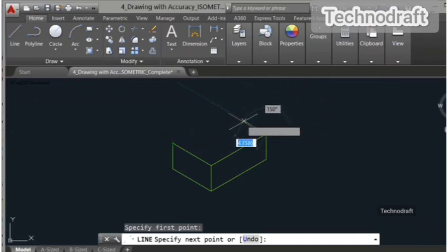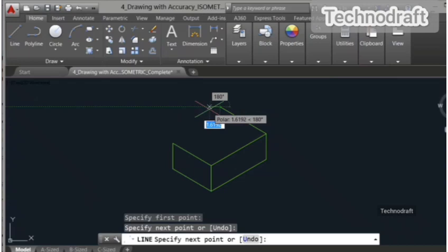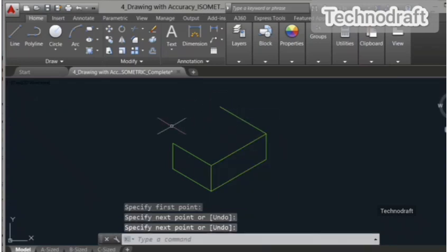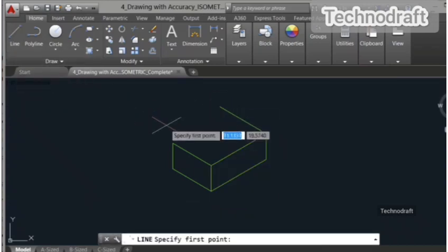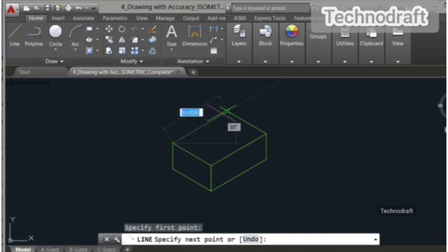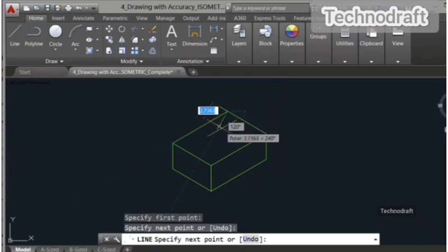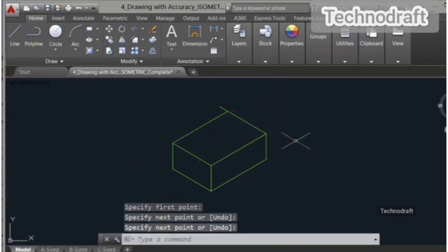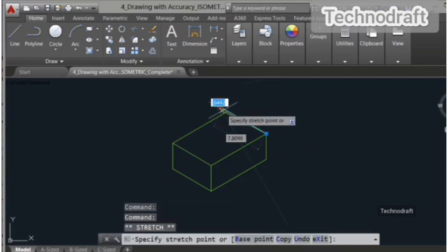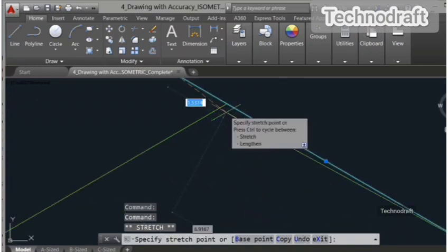Then what I do is I do a line, click, and now hover on this point here to get the object snap tracking, and as I come out this way I should get a line. Sometimes you don't, depending on which settings you have going on in your isoplane settings. But what I can do is just draw a line and then escape or right click to enter, and draw another line across to get the intersection.